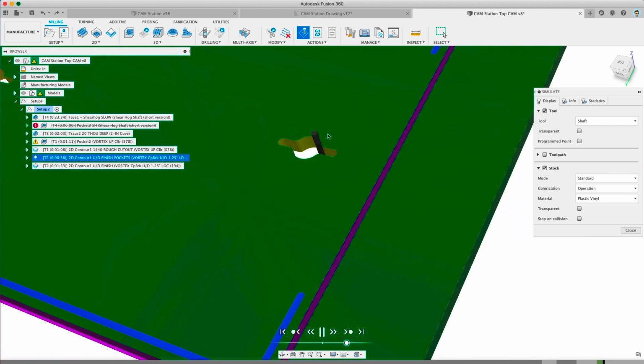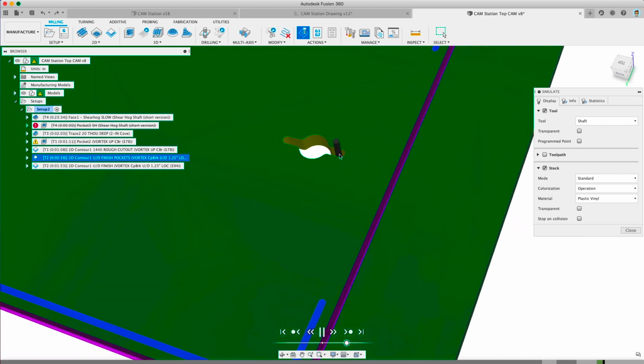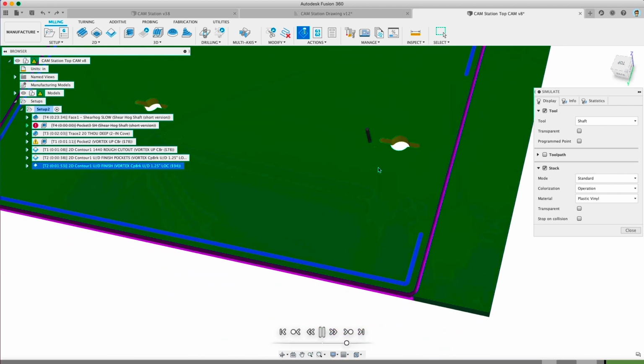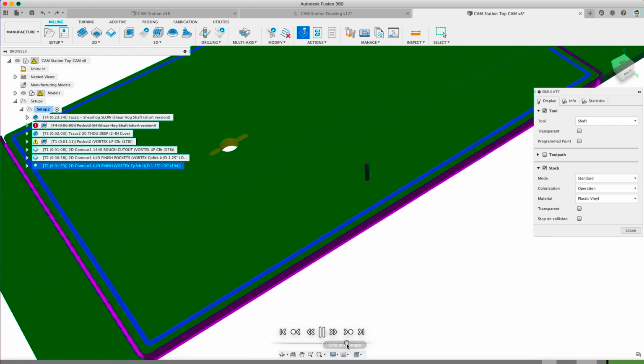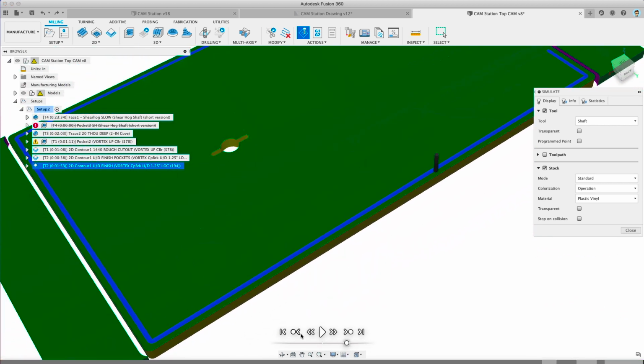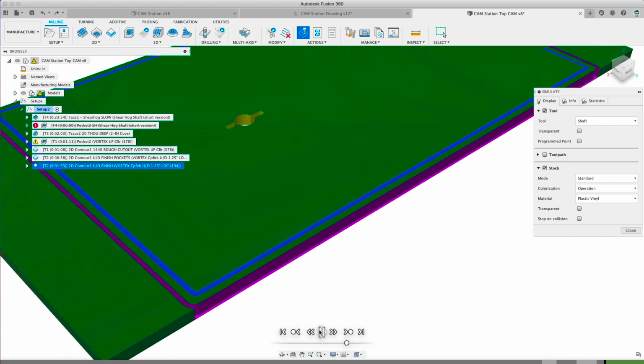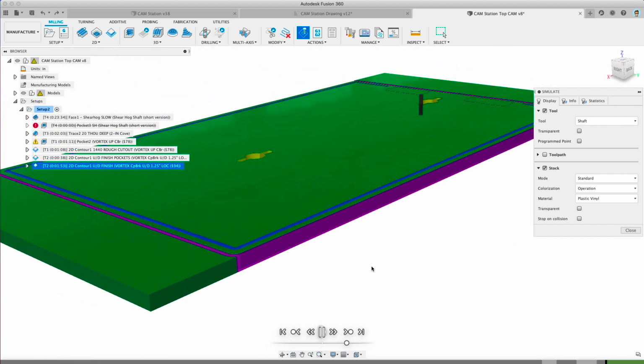I think I did a double pass or an overlap so that the ramp would get cut twice. I think I did them twice on the inside there. Those came out really nice and clean. So it did both of those. Now we're going to do the finish pass on the outside, and in warp speed, of course. You can see that stock to leave there.